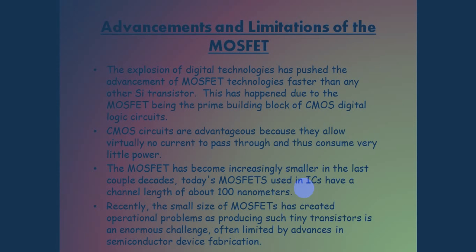Much smaller MOSFETs also offer some main advantages. The first advantage is that smaller MOSFETs allow more current to pass, since conceptually a MOSFET acts as a variable resistor in the on state, and a shorter resistor corresponds to less resistance and less energy being dissipated. Secondly, the gates are smaller, which means that the capacitance is lower, decreasing the time it takes the capacitor to charge, thus improving the switching time and increasing the processing power also. Lastly, smaller MOSFETs result in more transistors per chip, thus either increasing the processing power per chip or reducing the cost per chip.